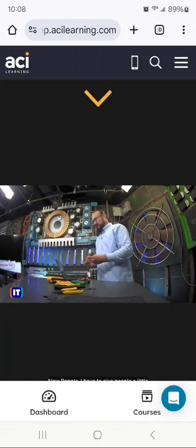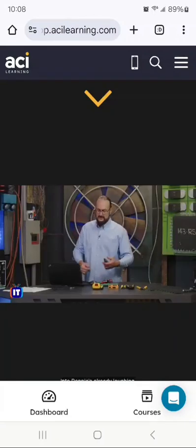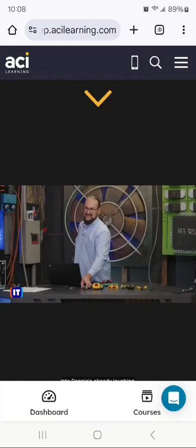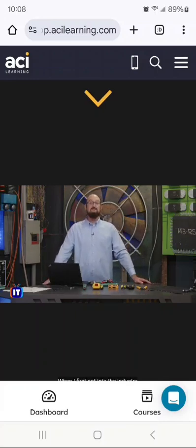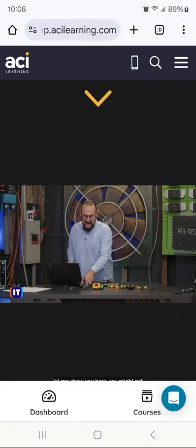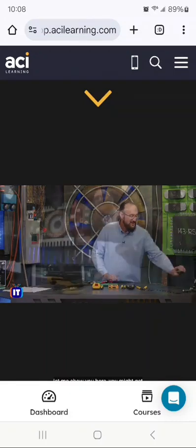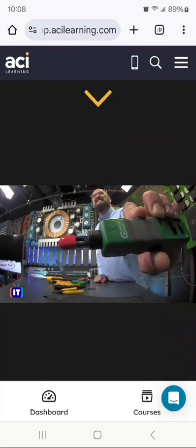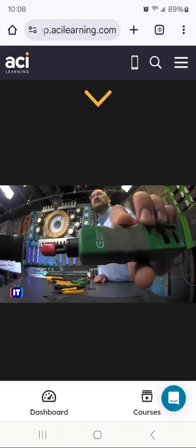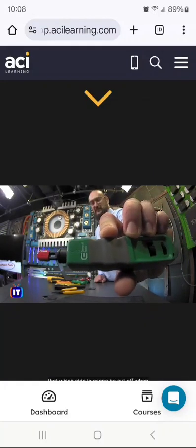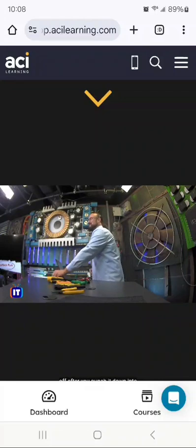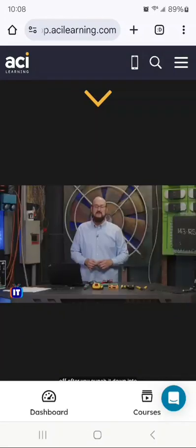Now, Ronnie, I have to give people a little bit of a warning here. When I first got into, well, Ronnie's already laughing. He knows where I'm going with this one. When I first got into the industry, I didn't pay attention to which side. And let me show you here. You might get a kick out of this. Do you see the little scissors option? That lets you know which side is going to be cut off when it comes to the excess that's trimmed off after you punch it down into the back of the patch panel.